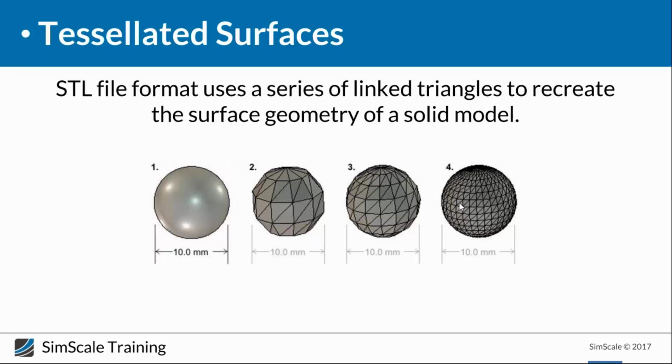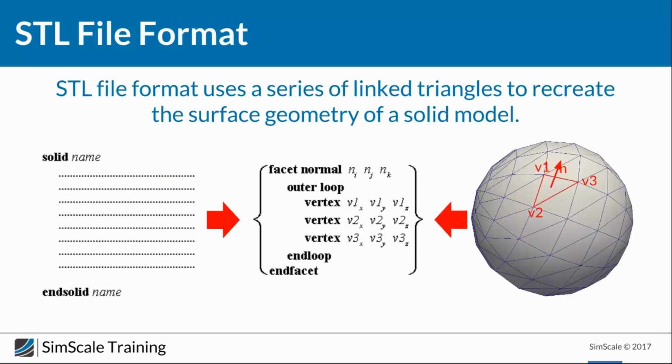Of course, this will also have some impact on the size of the file that you will extract later, but to get a good quality surface, you have to make sure that you have a higher number of elements to represent it. Now talking about the STL, and why we are talking precisely about the STL: as I mentioned before, STL is a really important format that you will face every day when you are working in CFD. So basically here we are talking about the formulation of the STL file.